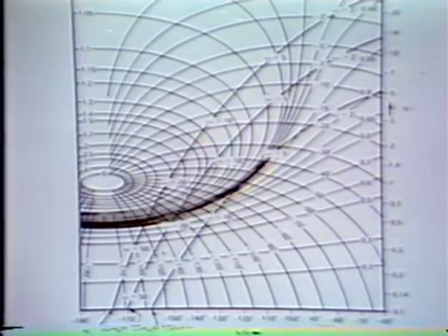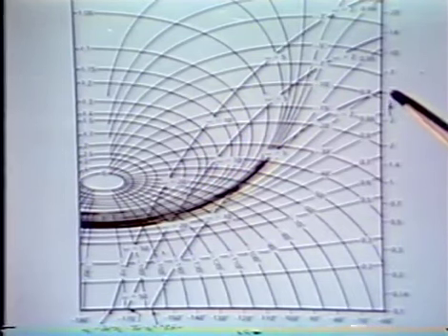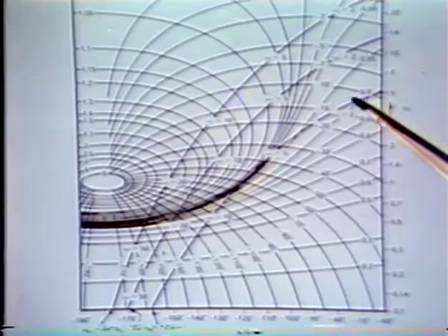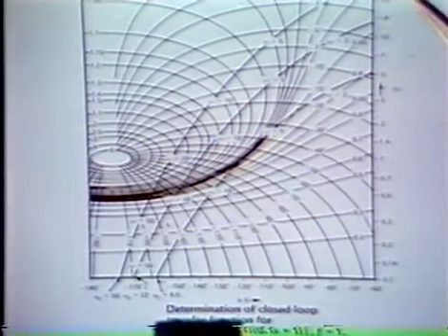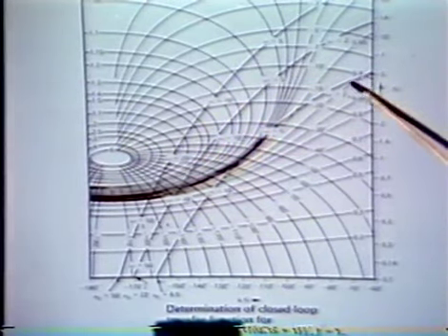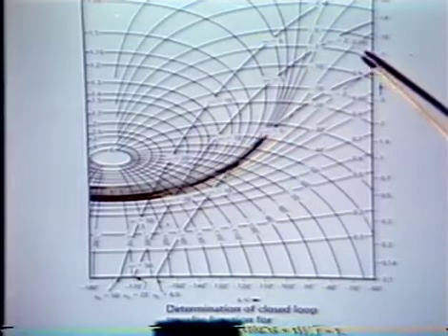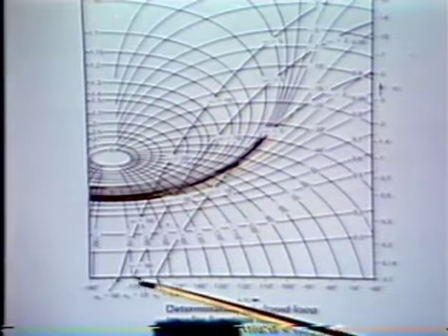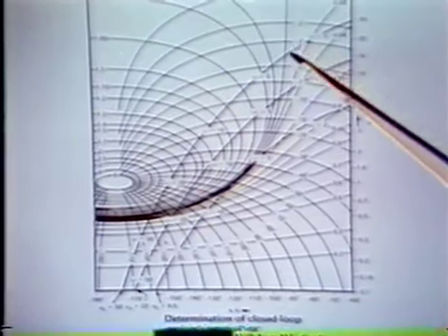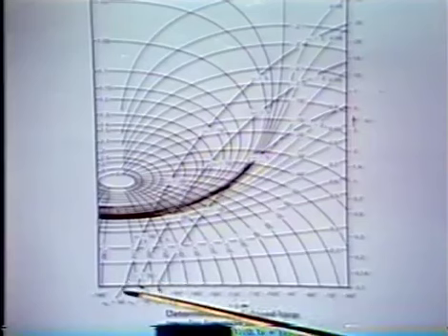We have a two-pole system, as you recall from the material on the blackboard, with a single pole on the negative real axis at s equals -1, another pole at s equals -10. And so we have a two-pole system, and what I've done is plot that transfer function for three different values of A0. Here's the curve that results for an A0 of 8.5. Here's the curve that results for an A0 of 22, the middle curve. And here's the curve that results for an A0 of 50.